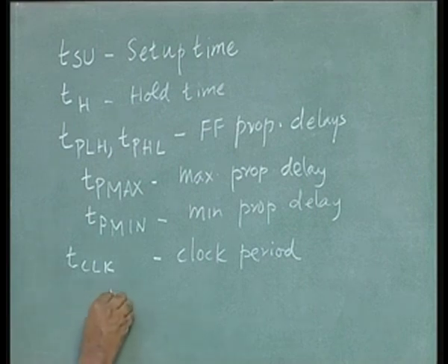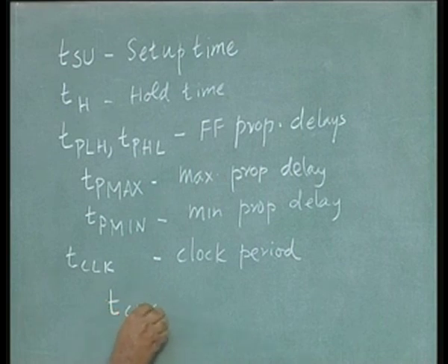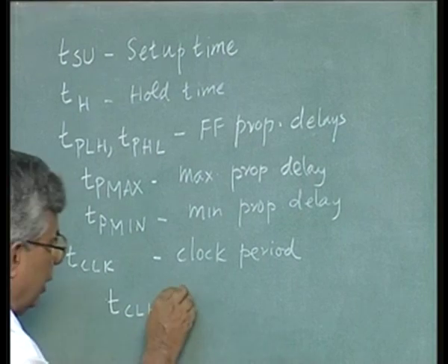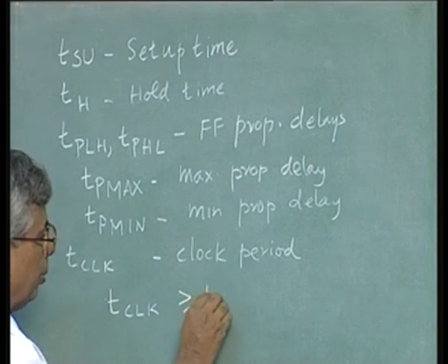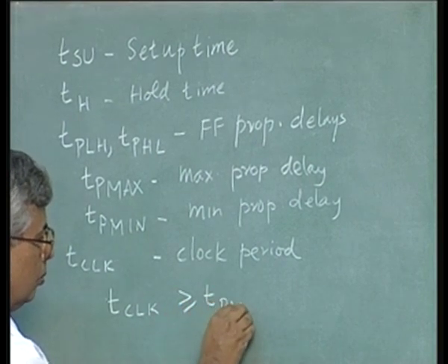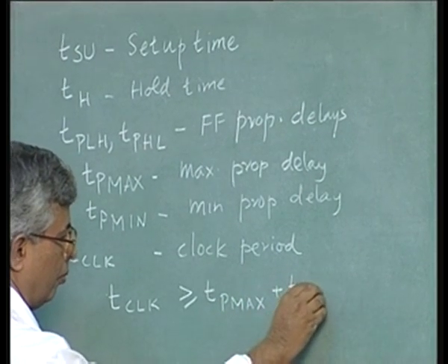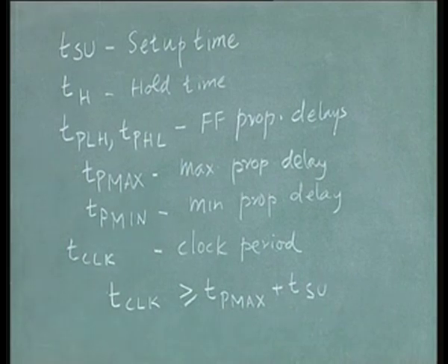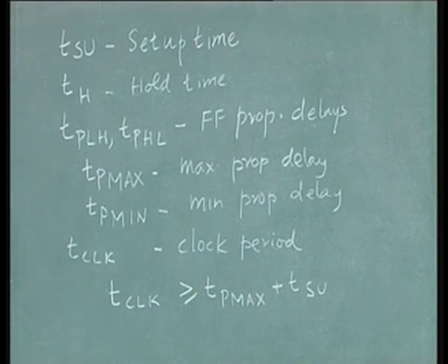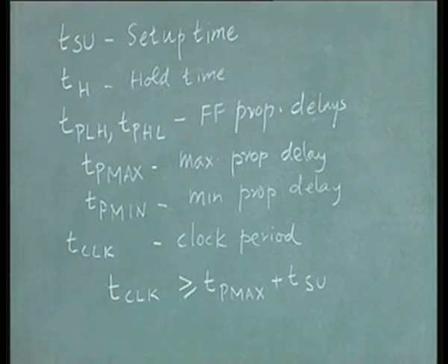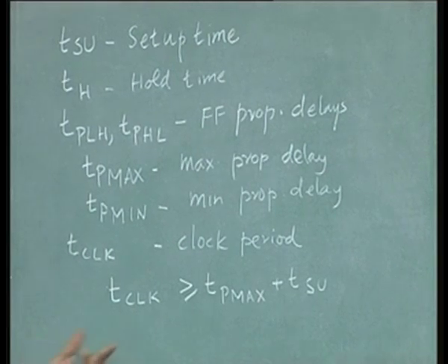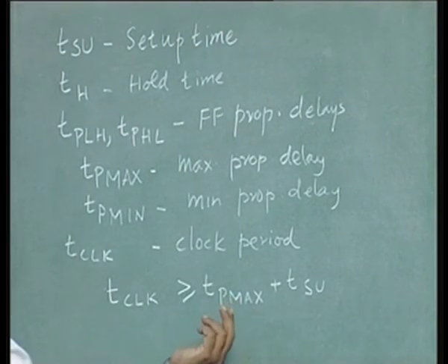T clock should be greater than or equal to TP maximum plus T setup time. Now you see, naturally this TP maximum need not come into the picture.